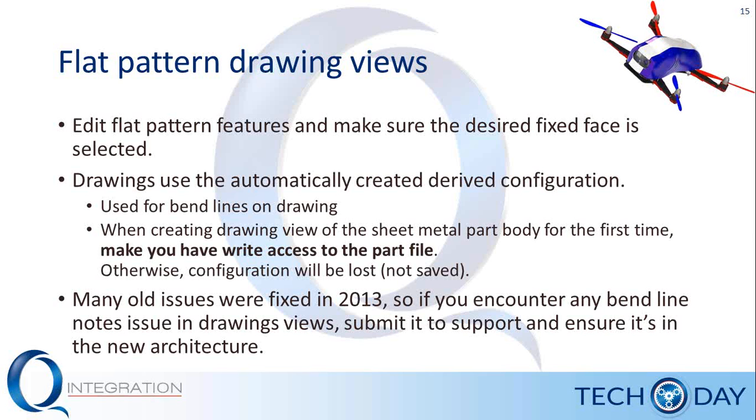Also, if you do need to reconfigure the orientation of that flat pattern view, you can edit the flat pattern in the part and specify your desired fixed face.